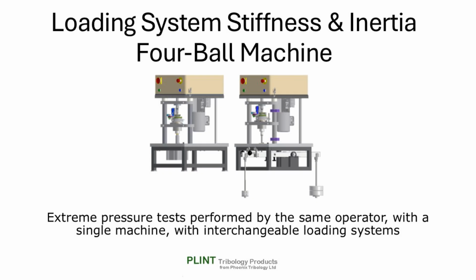More recently, we used one of our standard sliding 4-ball machines to provide a ready platform for comparing pneumatic loading with dead weight loading. Extreme pressure tests were performed by the same operator with a single machine with interchangeable loading systems.